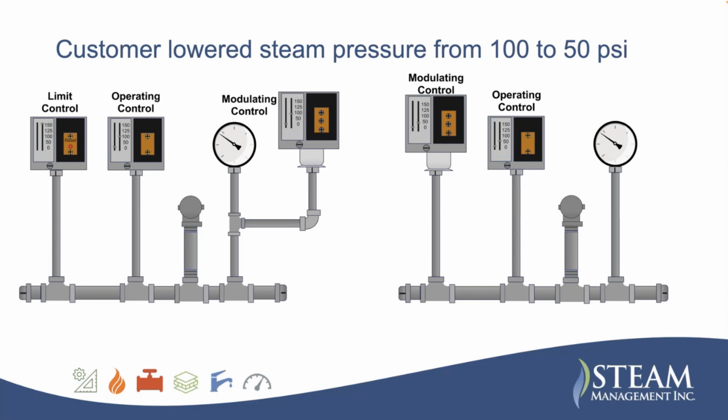Yeah, I mean, it's a great idea. You're going to save money with it, but you have to make sure you factor in the velocity. What I tell people to do before you implement something like this is do a little bit of an experiment. You're going to be the detective on the job. At 3 o'clock when the laundry closes down today, drop it down to 80 psi and see if it works without problems.